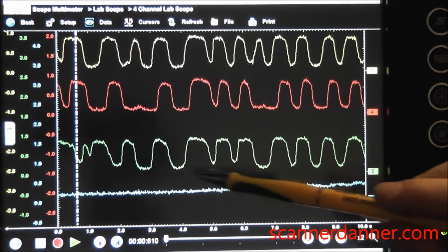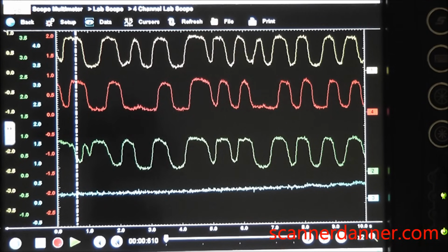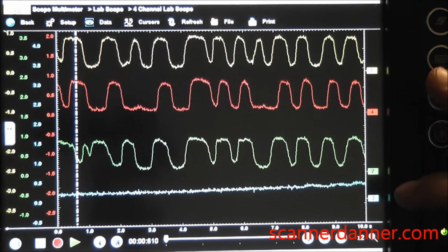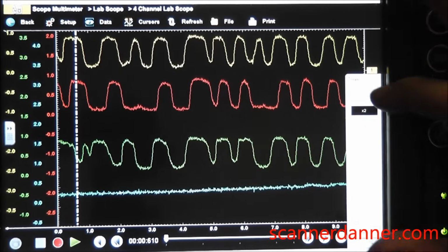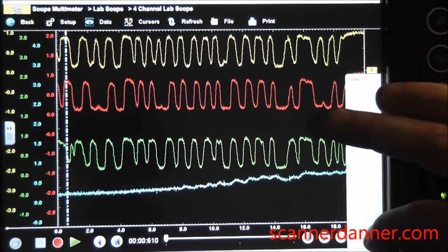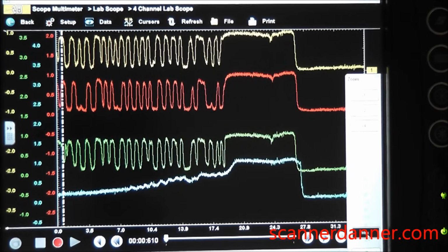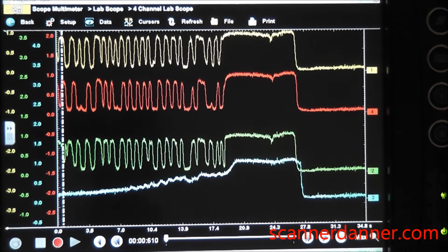You can have a cat that has a flatline signal at times and look like a good cat, but fail the OBD test for the cat. So the onboard computer fails it for efficiency. So maybe this test can help you with identifying those that look good as far as amplitude and frequency, but maybe they don't look good for an oxygen storage test.